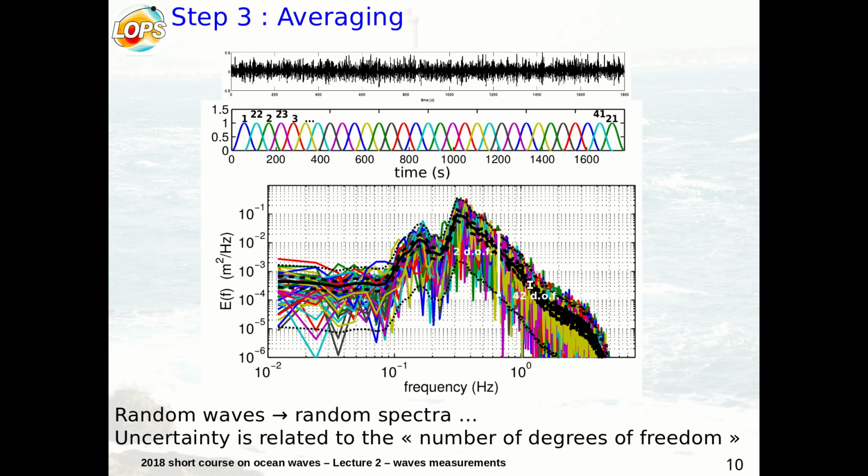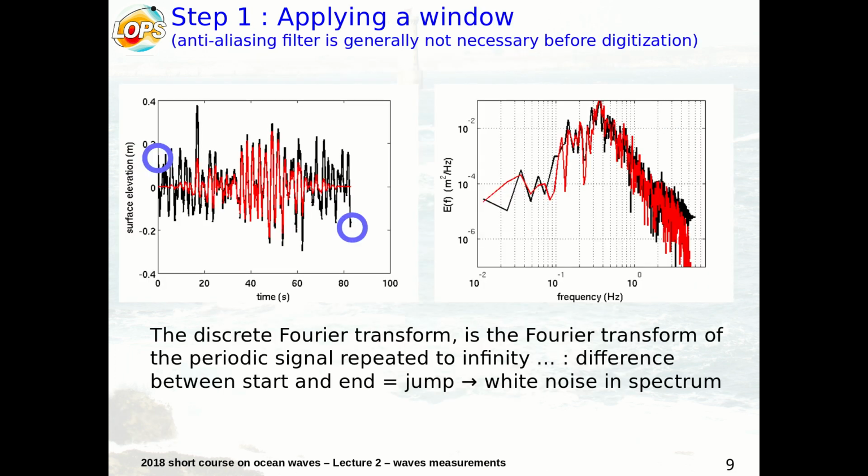I have a question about windowing. This is an old question I had from when I was working with images. When you apply a window, for example in the example the way you are showing there, does the window affect the whole signal or only the start and the end? Yeah, like this. The windowed signal goes to 0 in red, and so at the end it's not the same as the black yet. In the middle it's the same.